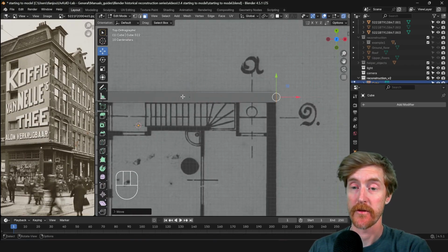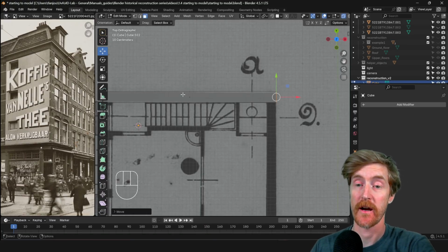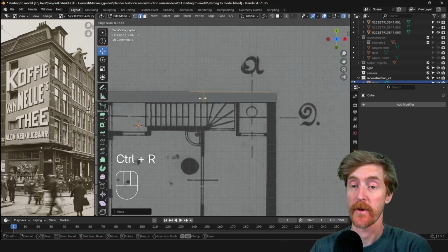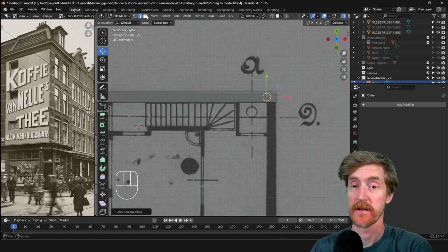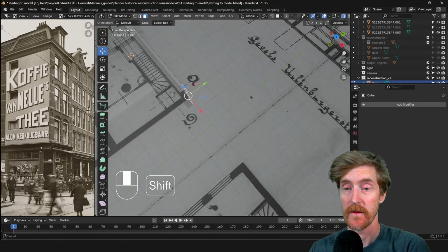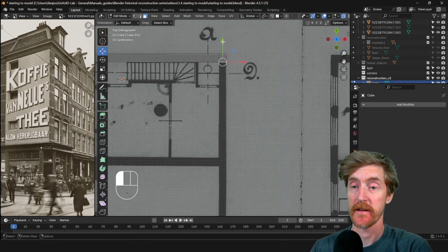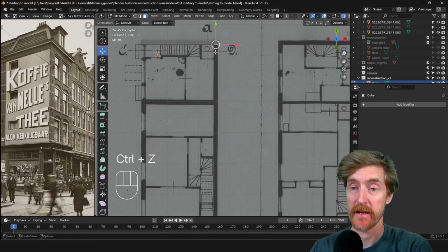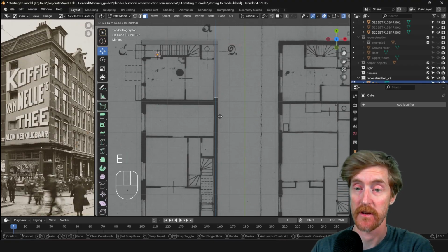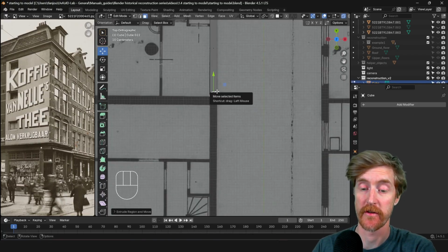Then to make the corner, I will use the loop cut technique again that we also discussed in this video, but I'm using a shortcut, Ctrl R, to quickly place a loop cut like this, and then selecting this face. And then I'm using another technique, because if I start moving like this, I get a diagonal line. That's not what I want. I want to extrude from this face downwards like so. So I use E for extrude. Extrusion is also a tool available to you here, but again, I'm using the shortcut E.